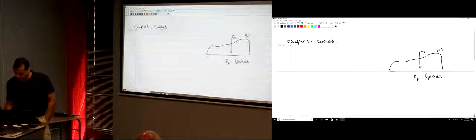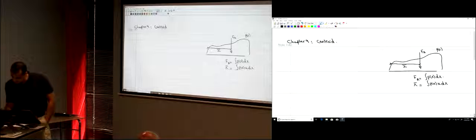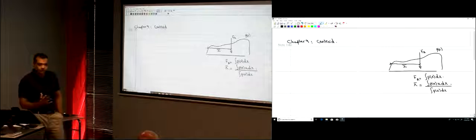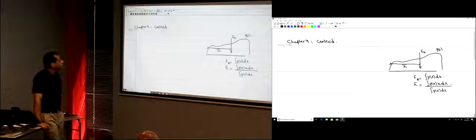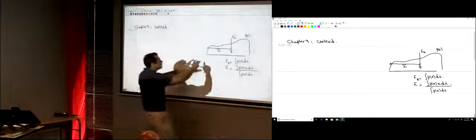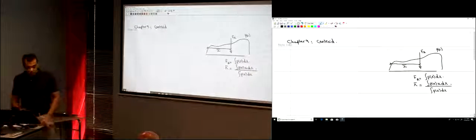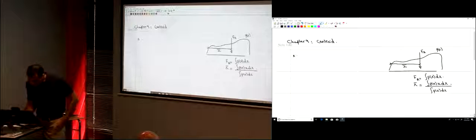And the location x bar is the integration of x p of x dx, divided by the integration of p of x dx. This location is the centroid of that load, or the center of gravity. So let's apply this same concept here. The force here, we have a distributed force that looks like this. So we're going to apply the same concept now.